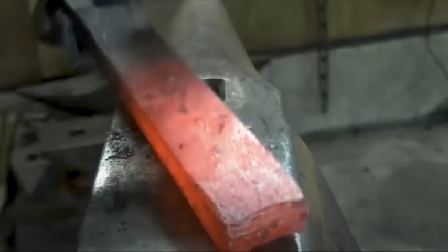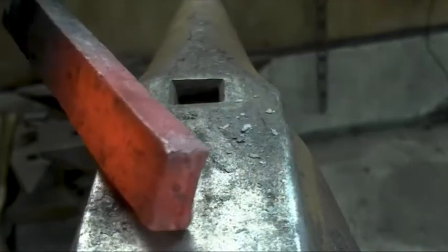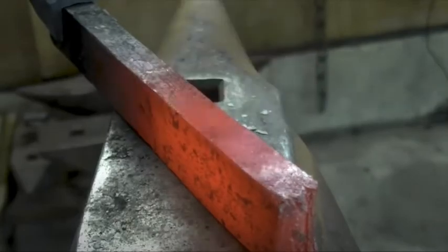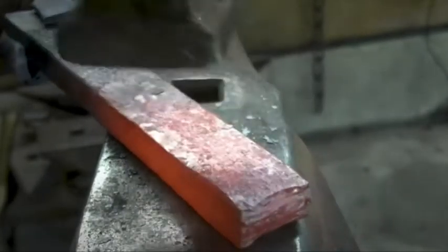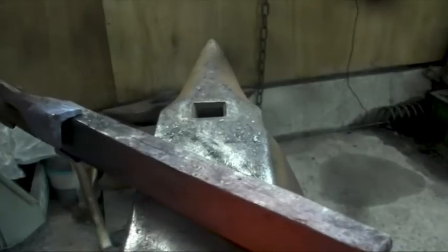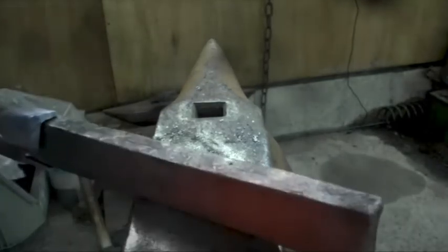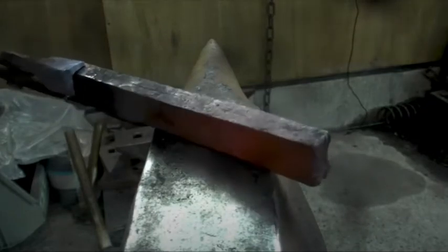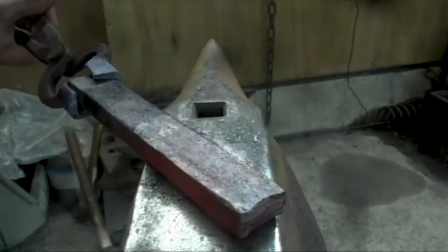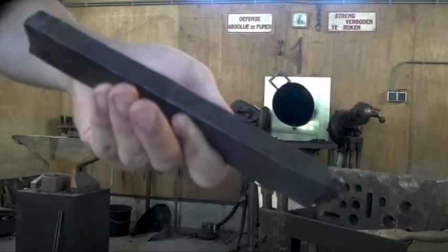First, mild steel. A low carbon steel containing from 0.15% to 0.25% carbon, also called soft steel. Second, medium steel. A carbon steel containing from 0.25% to 0.45% carbon. Third, hard steel. A high carbon steel containing from 0.45% to 0.85% carbon. Fourth, spring steel. A high carbon steel containing from 0.85% to 1.80% carbon.